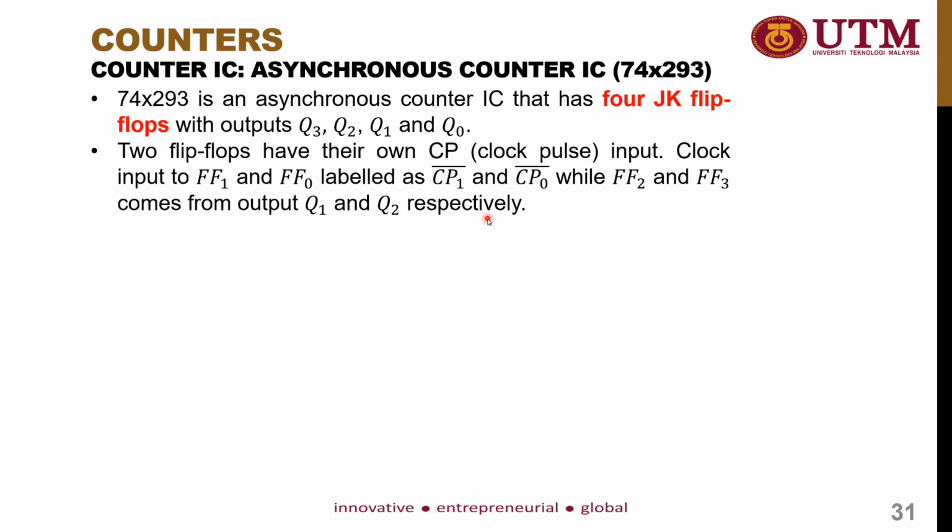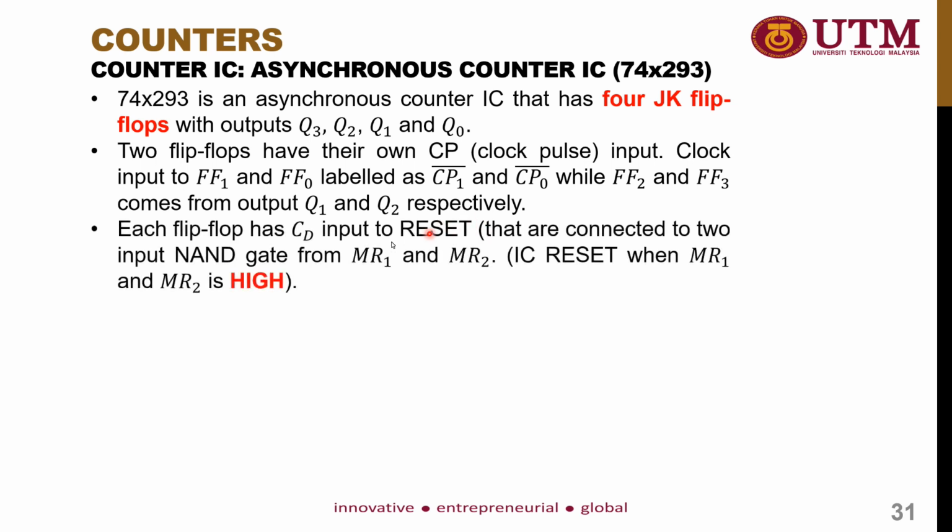So the first flip-flops have their own external clock pulse inputs, but for the later 2 flip-flops, the clock input is directly connected to the previous output Q. Each flip-flop has a CD input to reset, which is connected to a 2-input NAND gate from MR1 and MR2. So the IC resets when MR1 and MR2 are high.